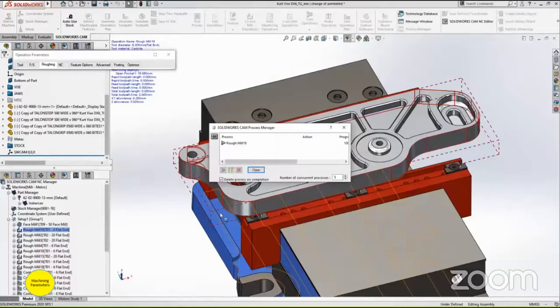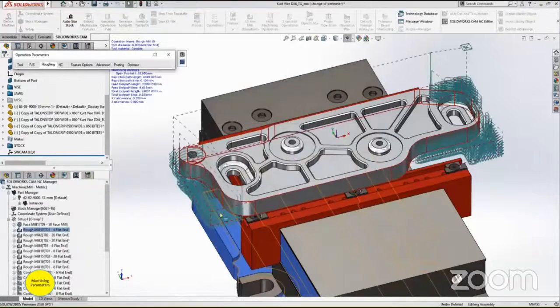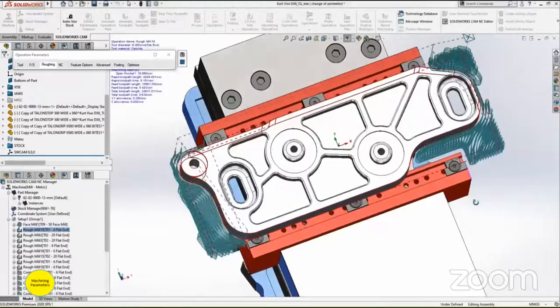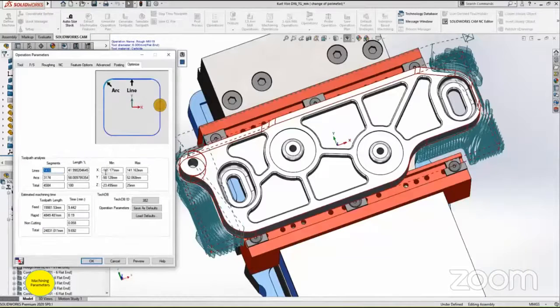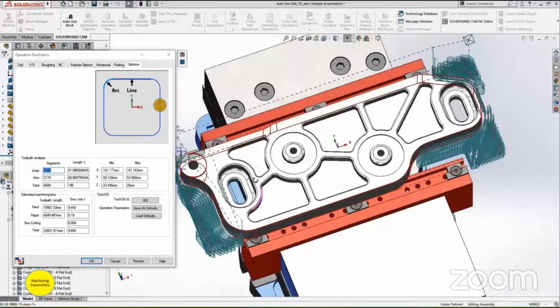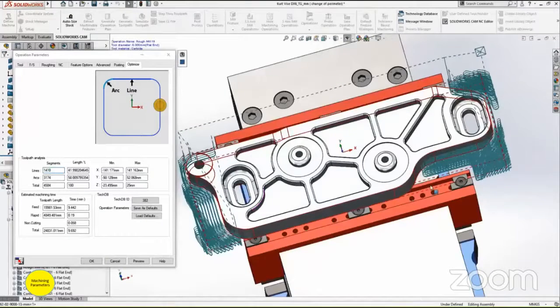But sometimes there are some limitations to this type of pattern. As we can see, it's not removing the material close to the fixtures, maybe because it's colliding with the fixtures. That's why, and it's taking 9 minutes, which is less than 12. But since it is not removing other material which is closer to the boundary, we can say that it's almost the same as pocket in.